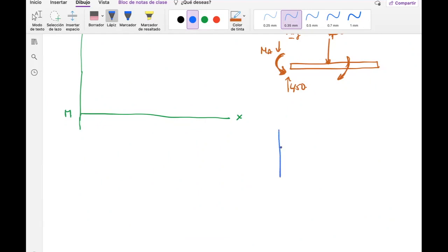This is again my triangle. Again, this is the breaking up of the beam, and this is my point A. This length is going to be X because it's something that you don't know. You don't know where you're breaking, or you don't care where you're breaking it. This is still 60 pounds per foot.